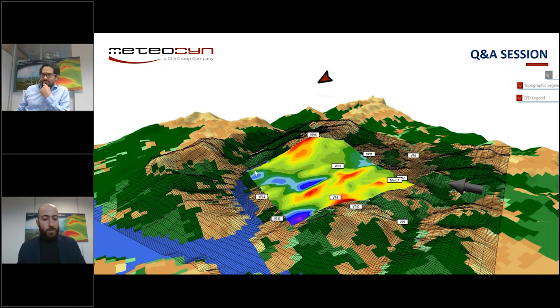Another question about the CFD turbulence model. Can WT use another RANS turbulence model such as k-omega? So no, not for the moment. We use a k-epsilon approach, using the RANS approach to solve the Navier-Stokes equations. And no, all the results are based on the k-epsilon model.